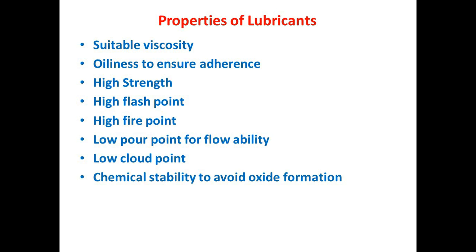So, definitely there will be a very small change in the viscosity of oil with respect to temperature. Next, we have the property which is oiliness. Oiliness is nothing but the property of lubricating oil to spread and attach itself firmly to the bearing surfaces as well as to provide the lubricity.